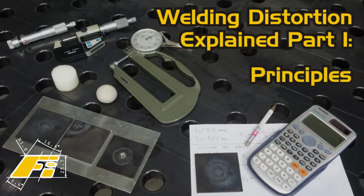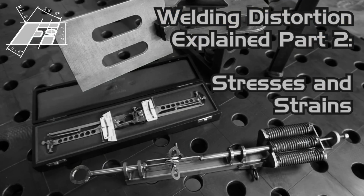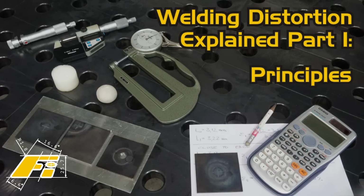During welding of a workpiece, countless processes take place in it. Most of them we cannot perceive with our 5 senses, such as microstructural transformations of the material or the formation of internal and residual stresses. This is probably the reason why welding distortion is so difficult to understand without the aid of particular experiments.